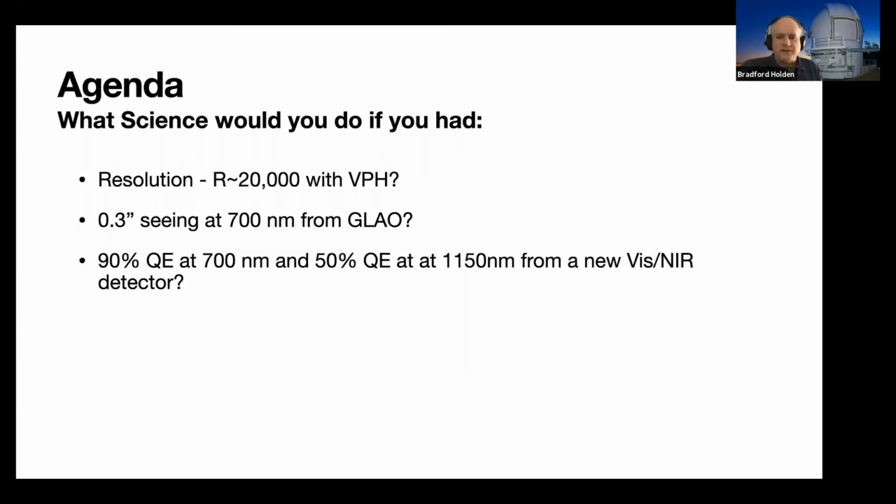And then the final thing is that there are potentially new technologies out there for detectors that work like CCDs, but have much higher quantum efficiency. They don't have the silicon cutoff because they're not made out of silicon. So you can possibly get maybe 50% or 40% absorption past the place where silicon becomes transparent at 1080 nanometers.